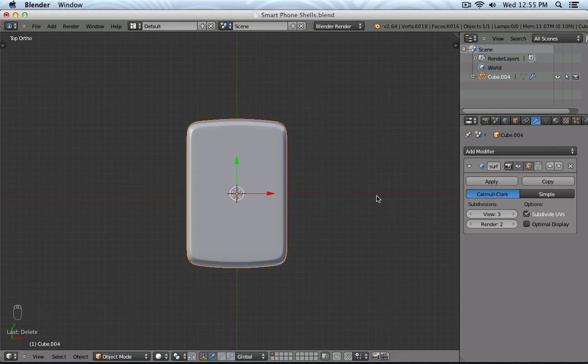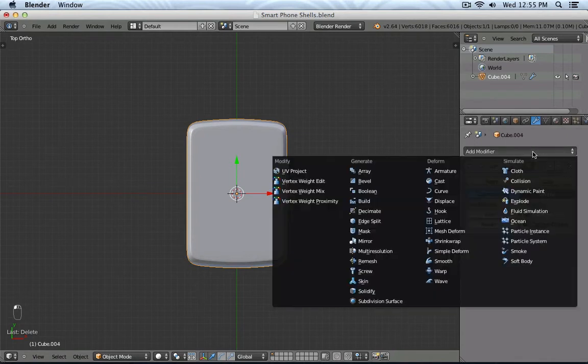In Alias, you have the layer symmetry, and in Blender, you do not have the layer symmetry. However, you have the object center symmetry. And that is a modifier. So with my object selected, I could go to modifier and then generate and go to a mirror.